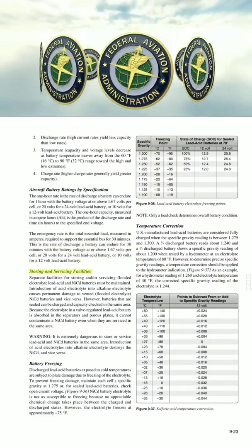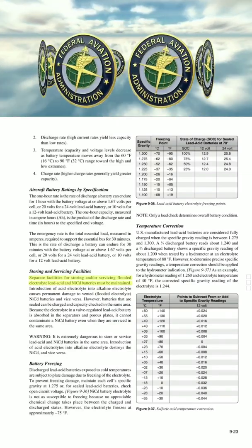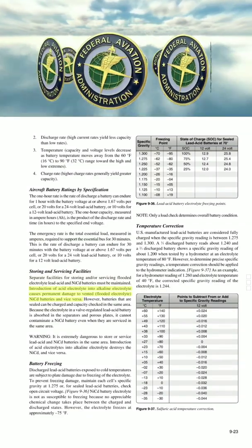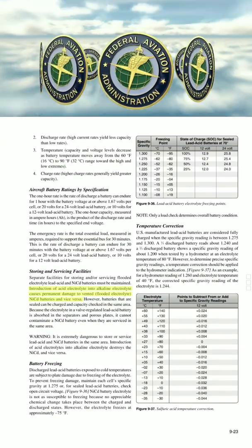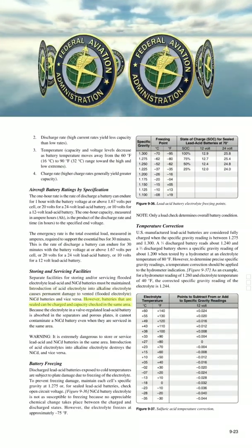Storing and servicing facilities. Separate facilities for storing and/or servicing flooded electrolyte lead-acid and NiCd batteries must be maintained. Introduction of acid electrolyte into alkaline electrolyte causes permanent damage to vented, flooded electrolyte NiCd batteries and vice versa. However, batteries that are sealed can be charged and capacity checked in the same area.